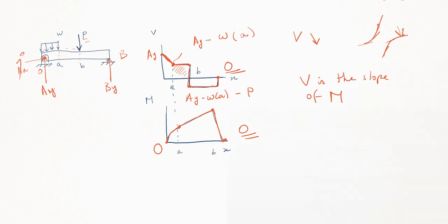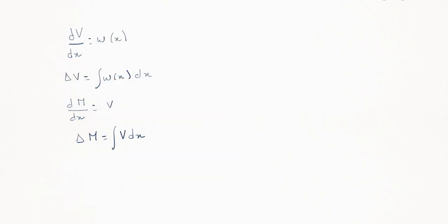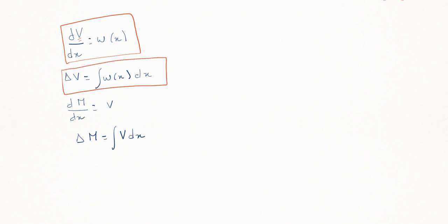Now moving on. So as I was discussing before, dV/dx is actually the distributed force, and if we want to get the shear from that, we simply do the integral. And the same thing, dM/dx is V.